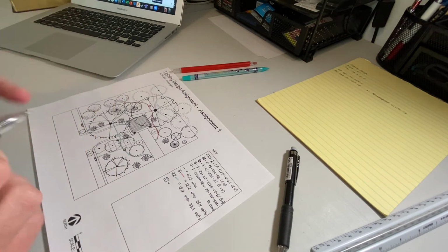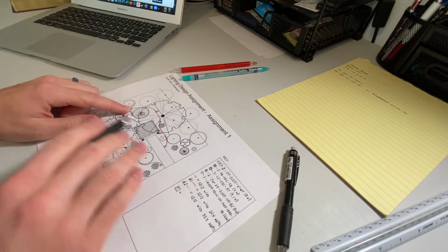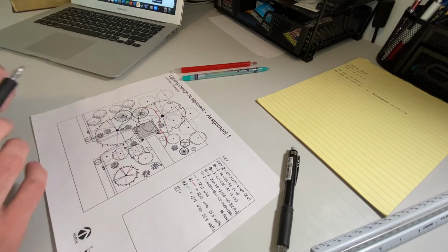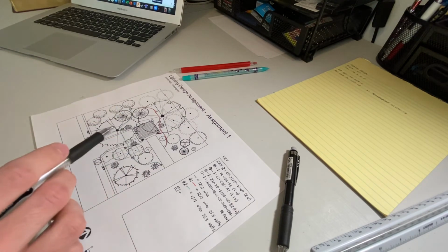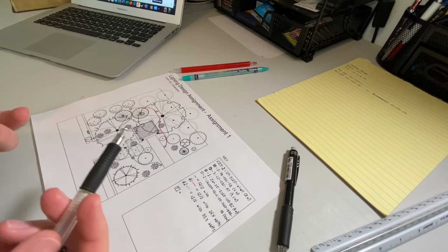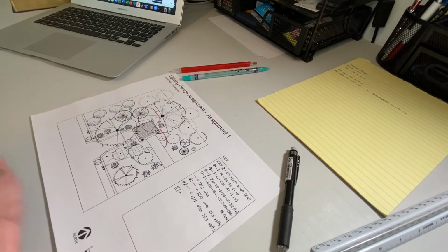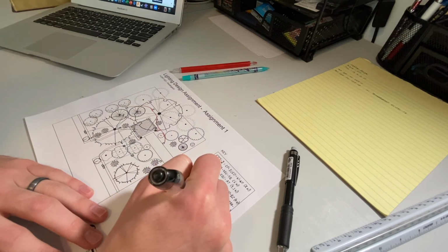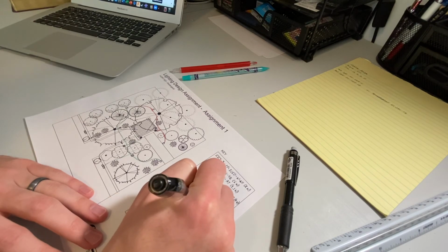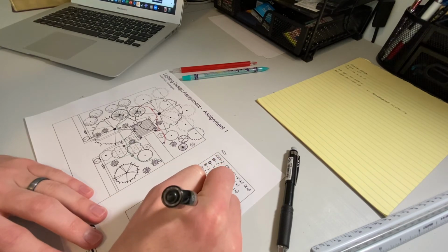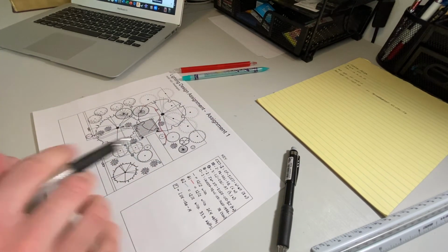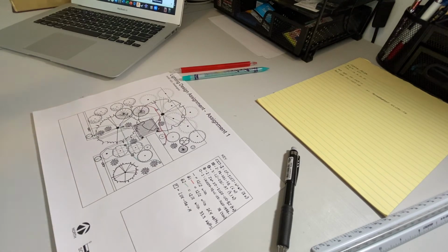luminaire zoning, dimming, and coloring transformer, because we put those kind of lights in the landscape. If we didn't get that kind of transformer, we got the cheaper transformer, it would still run, but these lights, you paid extra for the colored lights for nothing, and then they won't change color and stuff like that. So it's important to specify which kind of transformer you're using, so the installer doesn't mess up and waste money.